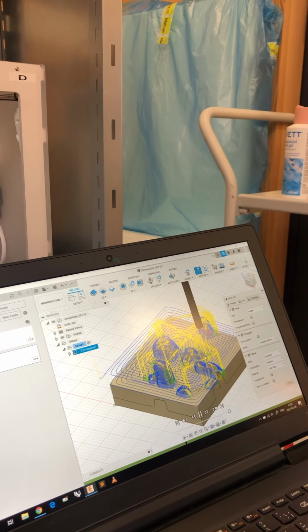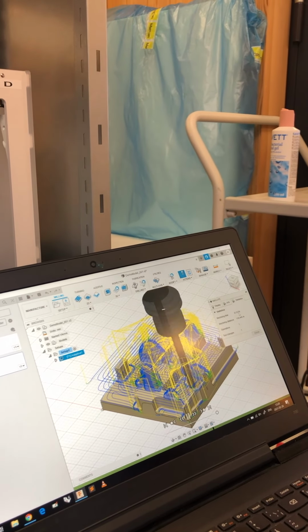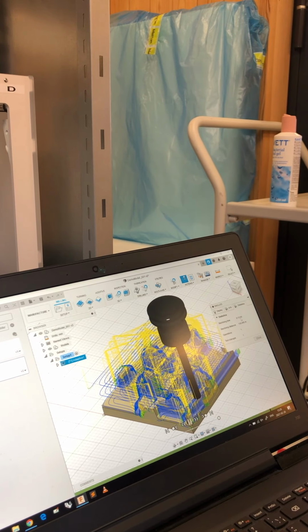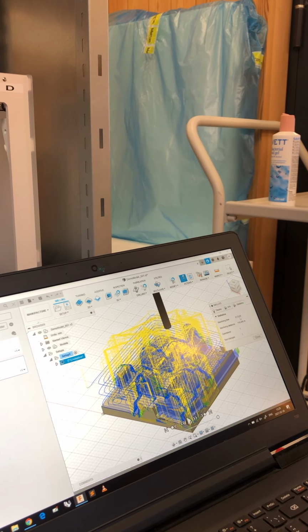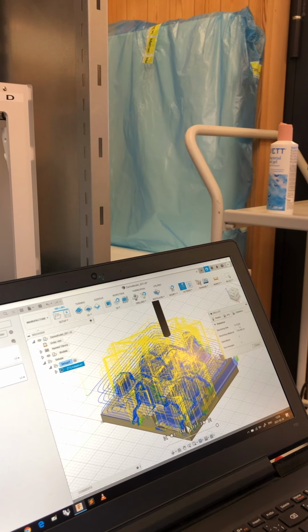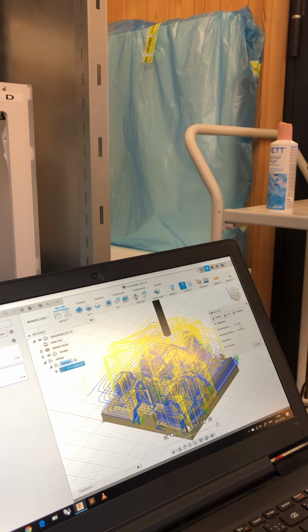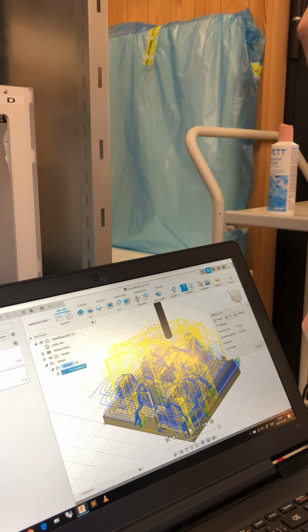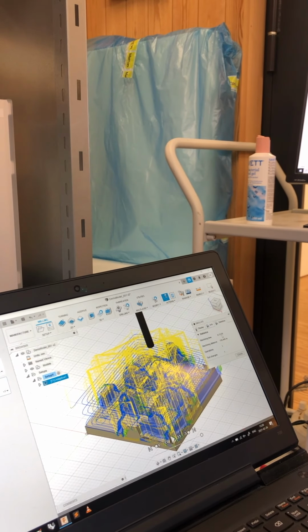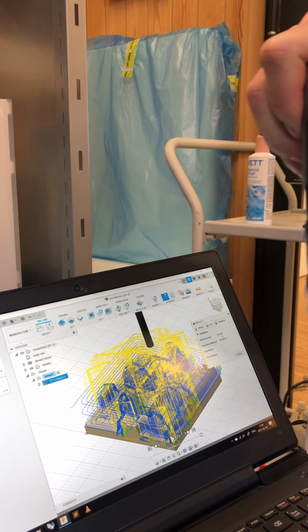and look at the statistics, because now it says that with 5,000 millimeters per minute, which is too high a speed for the styrofoam to be properly milled, because parts of the styrofoam will break off because the spindle is not rotating. It can of course be increased in its rotation, but 5,000 millimeters per minute is too much.